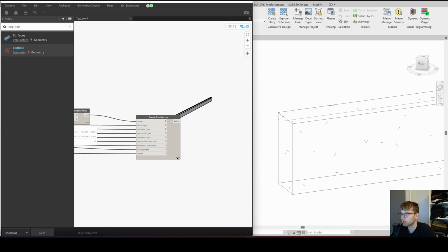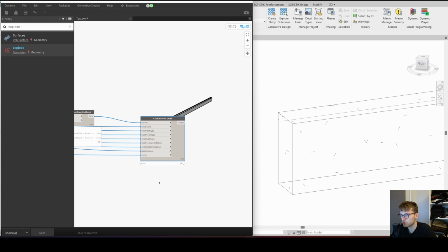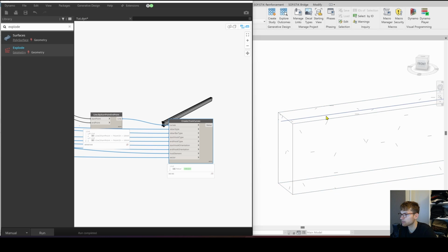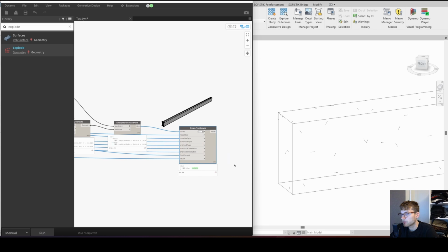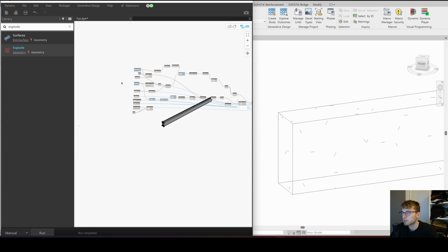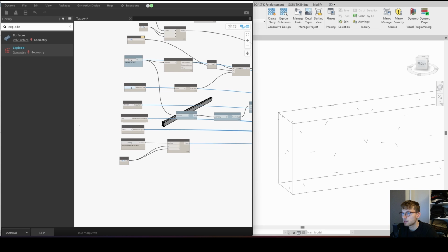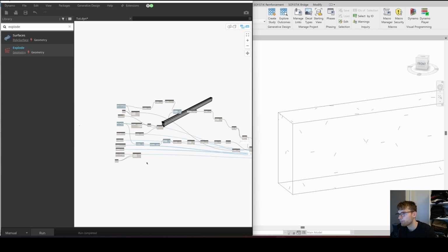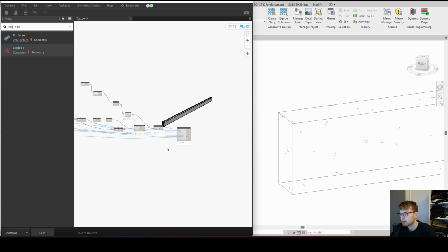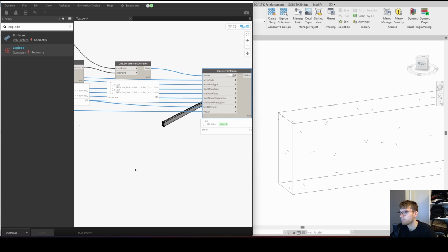Okay, now we got basically one rebar, but we have two lines that we want to get. Okay, let's just delete that again. And I need to introduce basically levels, and I think it should be level 2. Level 2. And let's see at the input again, because if we often delete something, then also the input is gone. Let's just select a rebar diameter again. And now let's execute it again. Yeah, so this time it worked as we wanted it. We got 2 rebars.